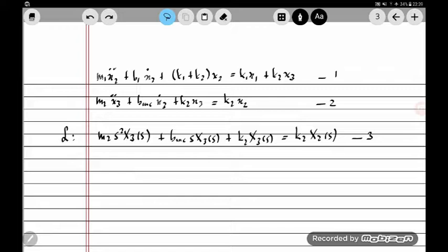What that means is we want to avoid using so-called differentiators, in other words, the Laplace variable s as a transfer function. We rather want to use 1 over s, which is called an integrator block, and this 1 over s is of course a strictly proper transfer function.